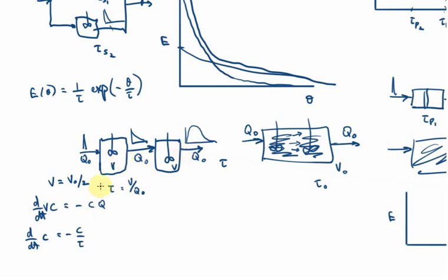So let's say this is the concentration from number 1. And now let's do the equivalent thing for number 2. If we write this balance on tank 2, we write d/dt of V C2 equals, and in this case, after t0, we can't say that the inlet is 0 anymore. The influence of this first tank is to exponentially decay the signal.